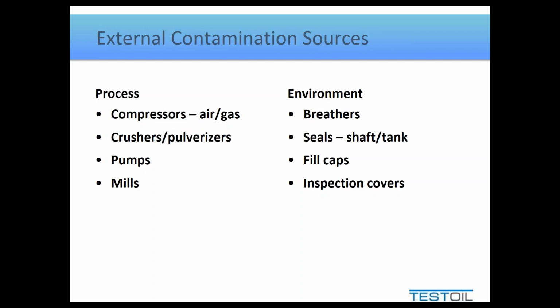Now, if we start compressing something other than air, we may now be compressing some form of chemical, and that chemical may have some negative reaction with it and may not be as clean as air. Not to say air is that clean, but some processes are far dirtier than just compressing air for instrument air or plant air. When we have other processes that are purposely creating particulate, like crushers and mills, well, then you're going to generate a lot more dust, and it's quite possible that some of that may enter past a seal into the lubricant, and it'll certainly enter the environment, and we'll see it come in through the breathers.